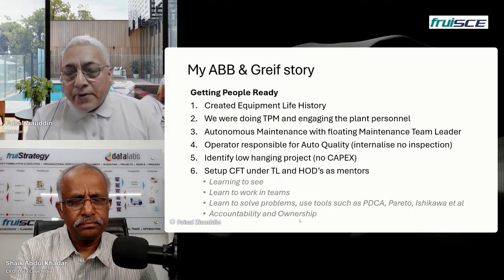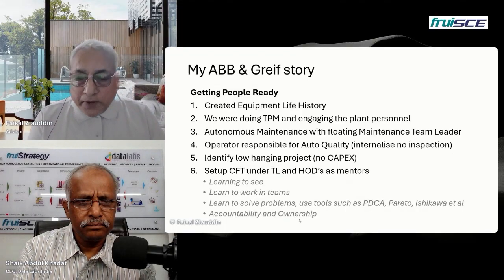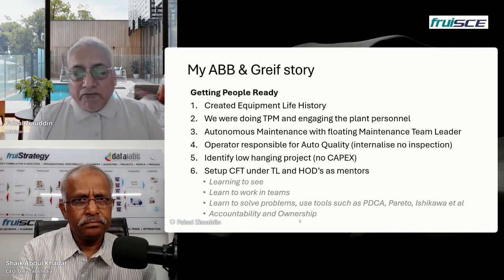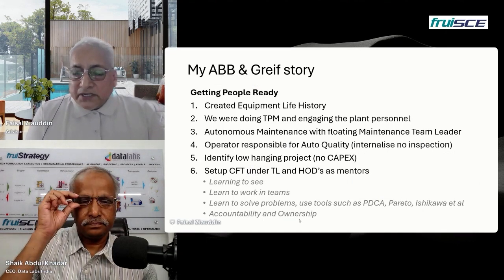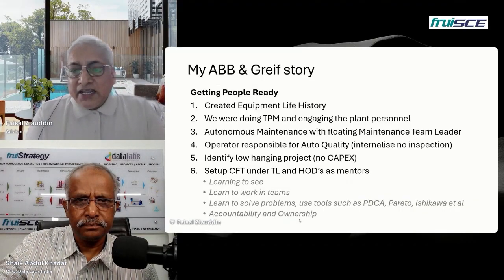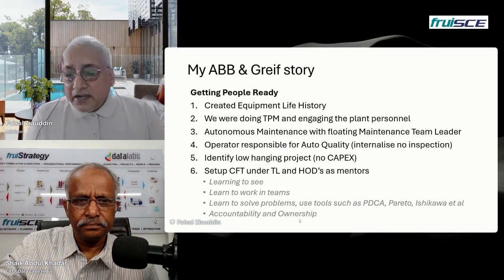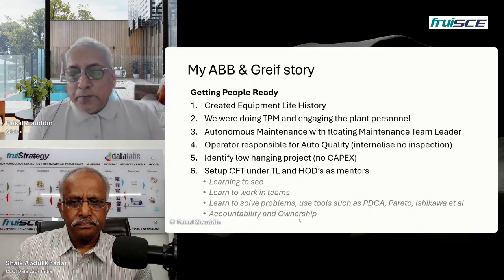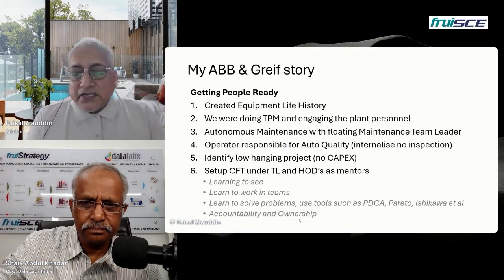And the primary onus of machine maintenance was with the machine operators, for that matter. Every day there was a daily discipline inculcated in all the team members, that every day you come at 8 o'clock, you do your CLIT. CLIT is the cleaning, lubrication, inspection, and tightening. Take around a 360 walk around the machine and see everything is in place, nothing is leaking, your bins are empty for the day, you are ready to go. So this task was like the first 30 minutes of every shift.